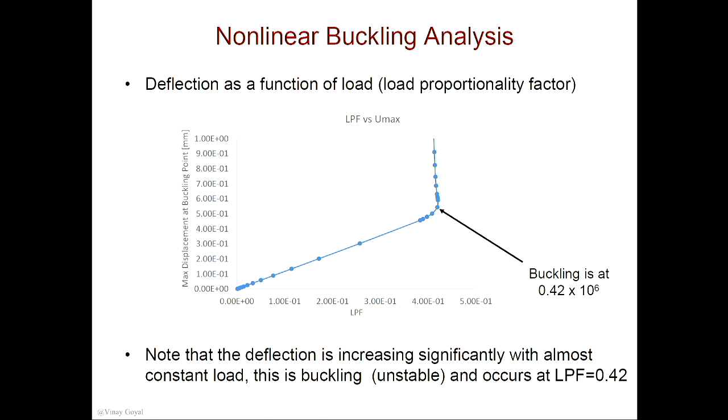The definition of buckling is you apply an axial load or you apply a load to a structure, and with a small amount of increasing loading, you have a huge amount of deflection that occurs. That's what buckling is. In your scenario for the can, you applied a load, although you did it dynamically, you put a really large force. The whole thing went, right? It just crushed. If you try that with a ruler, it's going to just break in half. Okay, but there you go.